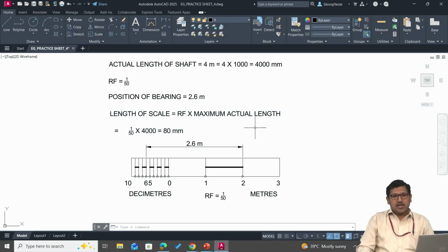So what is important here is, we need to be able to find out the length of scale, and this can be done only after converting the major unit into its smallest unit or division. Then we need to divide the length of scale into some number of equal parts as per the given data, and the first main division should be divided into subunits, and afterwards we need to locate the given distance on the scale. The other important point is it is equally important for us to show the main unit and its subunit and RF as part of this solution.